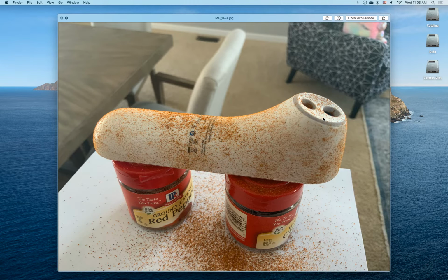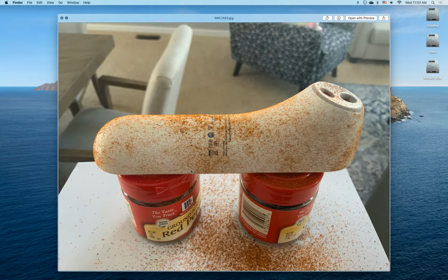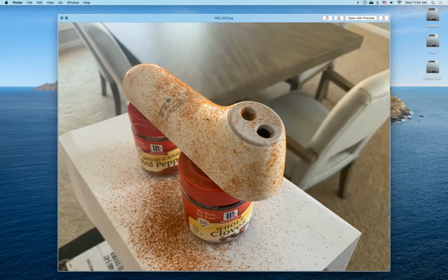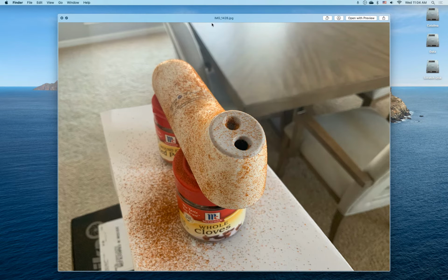So you also see this object is elevated off the ground. The reason why I did this, it helps to separate the object from the paper, and I will end up with a really nice sharp edge. So I started taking the photo from the side, and then I slowly walk around. And there you can see there's a reflection of the sun, the window. So I try to keep this out of the image. I try to frame my object as much as possible. The more pixels the thermometer occupies, the more pixels the software can work with and use to create a mesh model.